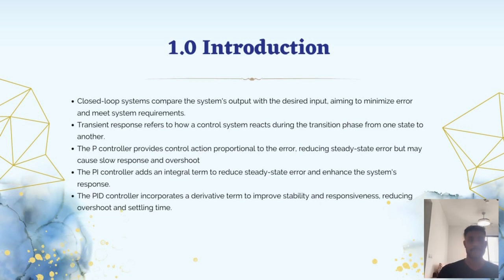And as we're using MATLAB, we're going to use the PID tuner in our Simulink. Simulink is a kind of app which we can use to modify or design our own systems in MATLAB. The PID tuner allows engineers to design to transient response requirements, which initially generates the controller parameter values. It means we can set up our own values in the PID tuner to get a perfect transient response.